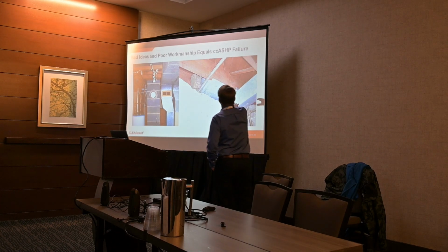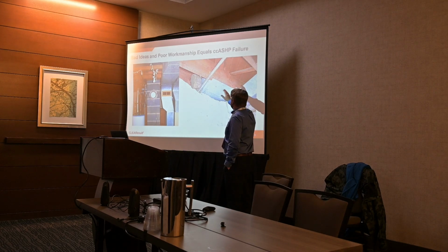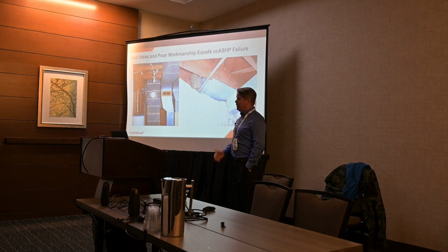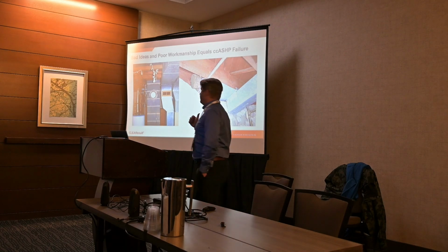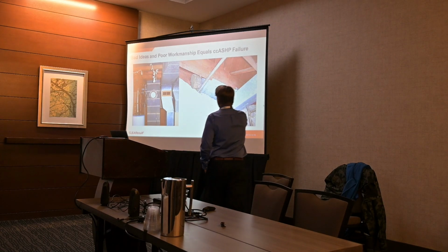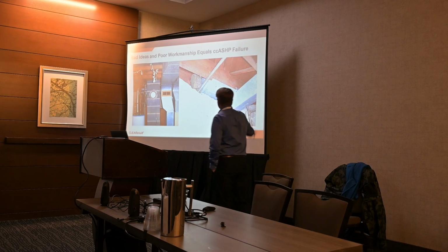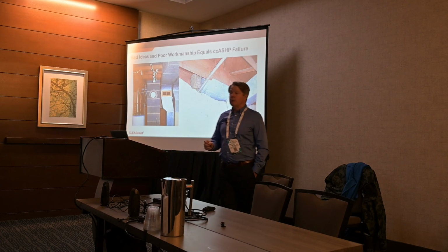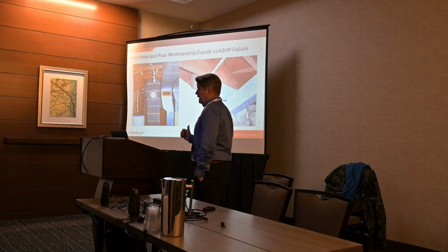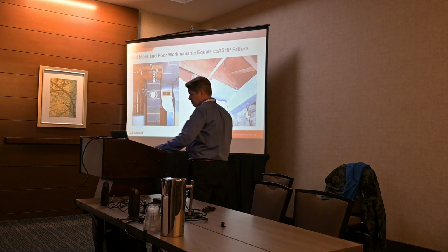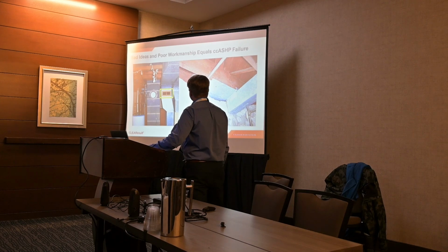We can't have this. We have to have tight ducts. Obviously, that's against code now, but it wasn't. But we can't have that kind of stuff going on. We have to take all the air from the conditioned space, because it's 70 degrees, and we have to push it back into there, because we need that 30-degree temperature rise to get to 100 degrees. We can't come to 80, okay? It's not gonna work. Close that, remove it, and seal it permanently.